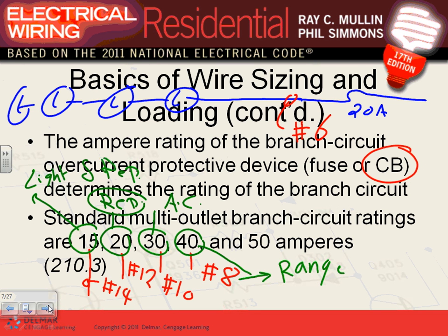So your light wouldn't work, and if it works, it would malfunction, and if it works and doesn't malfunction, it will die prematurely. Equipment either doesn't work when you give it low voltage, or it works inefficiently, or it dies on you prematurely because of under or over voltage.